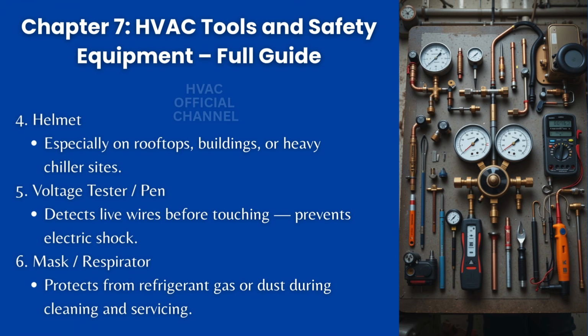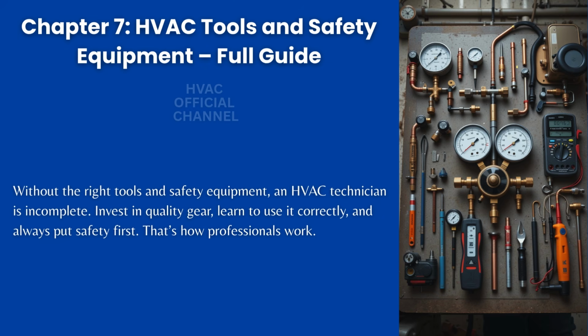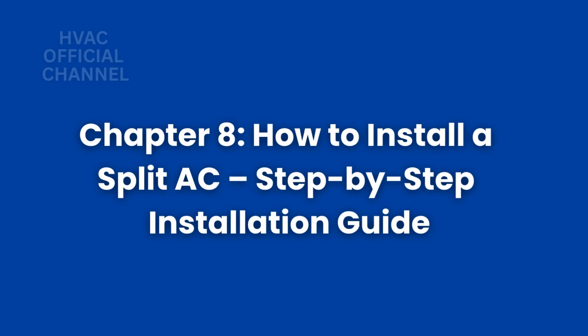5. Voltage tester pen. Detects live wires before touching. Prevents electric shock. 6. Mask/respirator protects from refrigerant gas or dust during cleaning and servicing. Without the right tools and safety equipment, an HVAC technician is incomplete. Invest in quality gear, learn to use it correctly, and always put safety first. That's how professionals work.